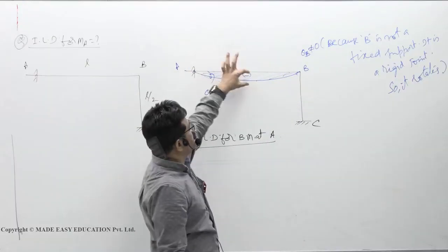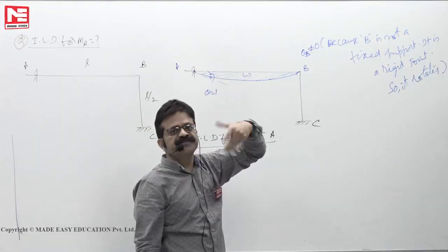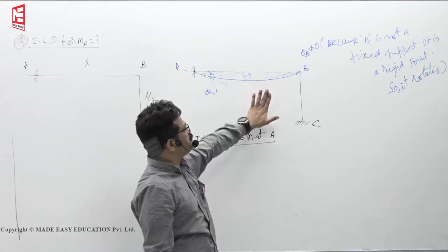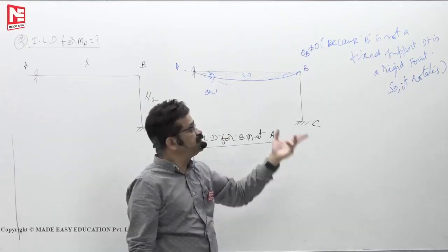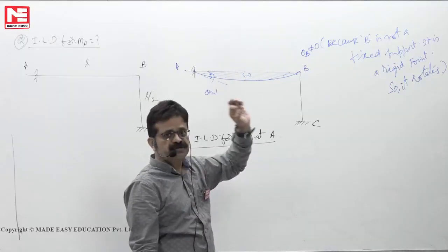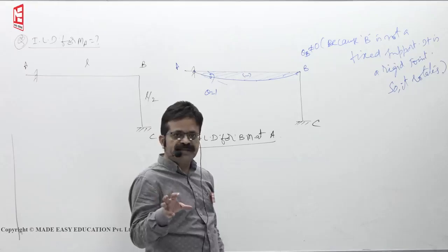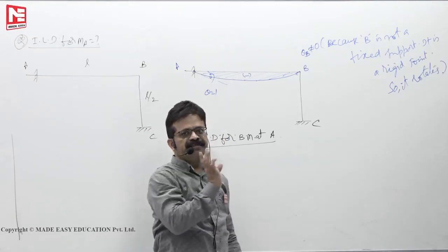Then what is the maximum ordinate, at what distance it happens is a conventional question, 15 marks question. The mains we will see that part. Now prelims part, how the shape looks like and how to get the value they can ask. You must use moment distribution or slope deflection method. That means those methods can be used to find the ILD ordinates in the indeterminate structures.